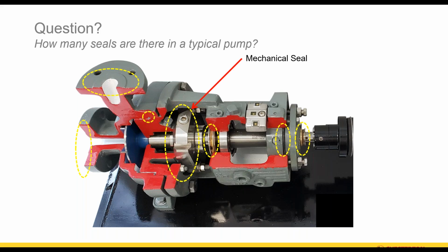Today, we're going to talk about the mechanical seal, which is what would be considered the main seal to the shaft. But the reality is any one of those seals can fail and cause excessive leakage. And you need to recognize that too, because many times a mechanical seal is blamed when it's not even the issue.